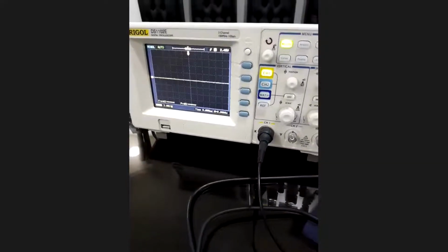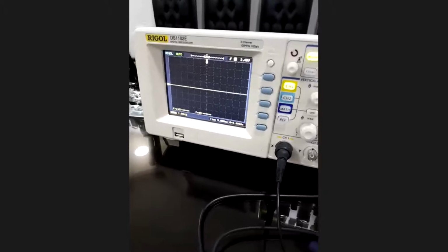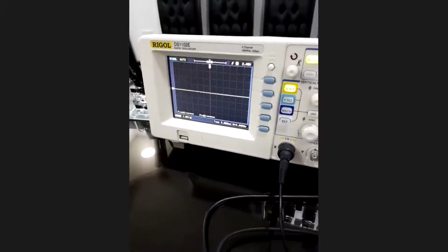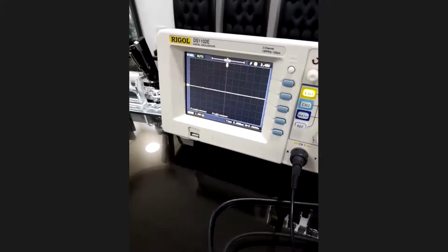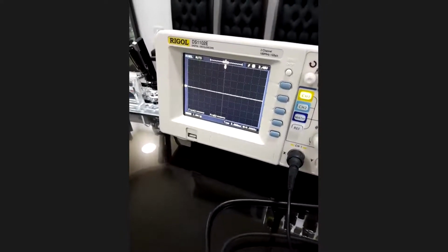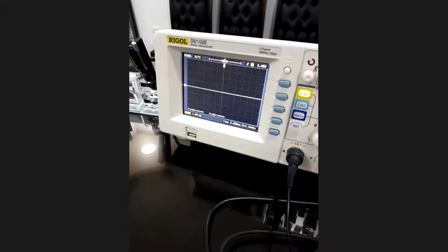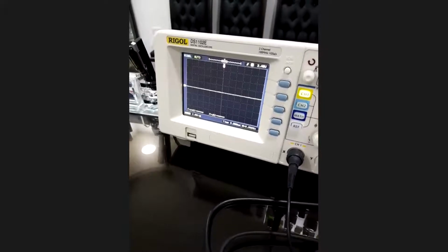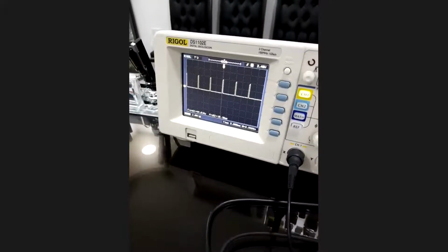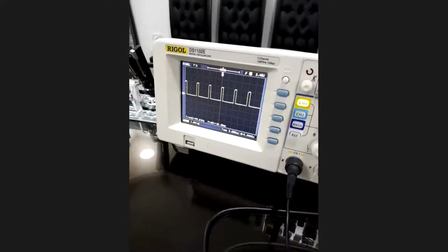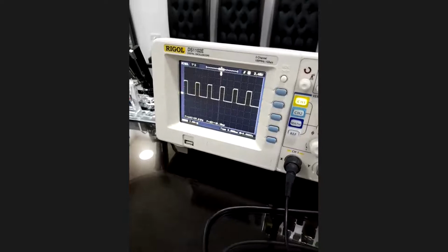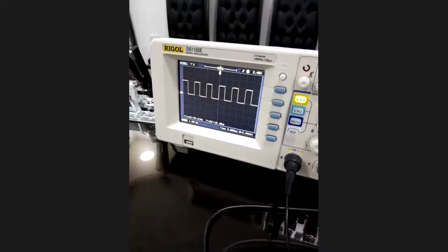It's connected to a motor through an NMOS transistor, similar to what we did in the motor example when we used the model based with Arduino. It will stop. I'm going to start turning right, and I start getting a PWM signal. See the pulse width? It's increasing as I turn right, it keeps increasing.